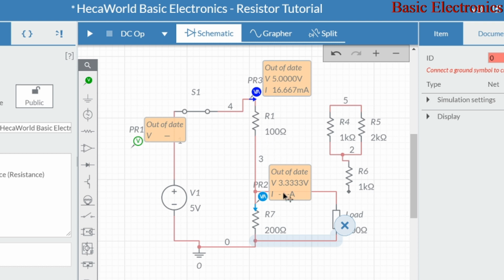It doesn't have to be 100 ohms. It could be 1000 versus 2000. It can be 4000 versus 8000. Whatever value you get, twice that size. The important thing here is the ratio. Once the ratio is 1:2, the voltage will be divided in that order as well.